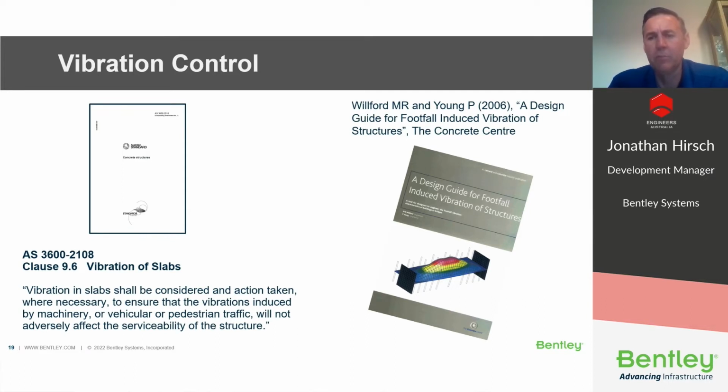While there are several simplistic methods to calculate vibration acceptability, they're often too approximate for complex irregular floors that are common in concrete construction. So the approach outlined in the design guide shown is generic and comprehensive and applies regardless of geometry and materials. So it can be used on concrete structures, steel structures, or a mixture of the two, and can accommodate any geometry.